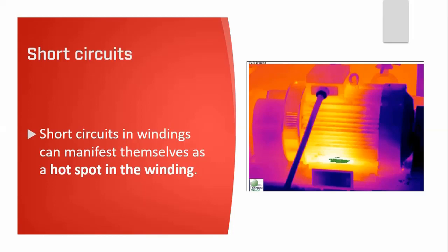As a rule of thumb, it is admitted that for each 10 degrees C below the rated temperature, the life will double. And for each 10 degrees above, the life will be halved. Of course, other factors affect the temperature life of the motor.